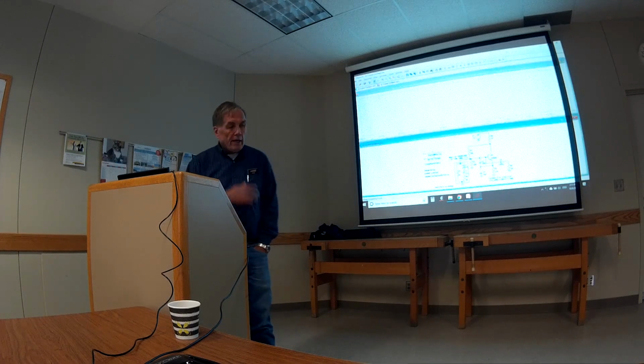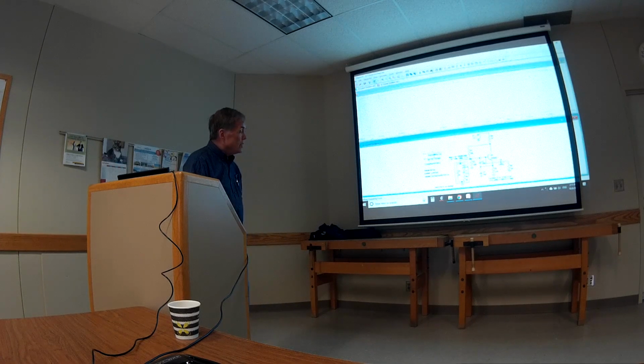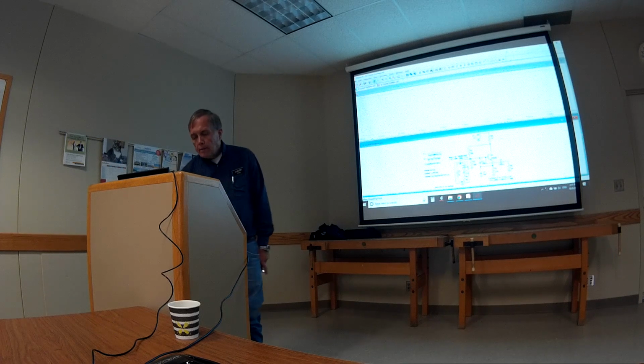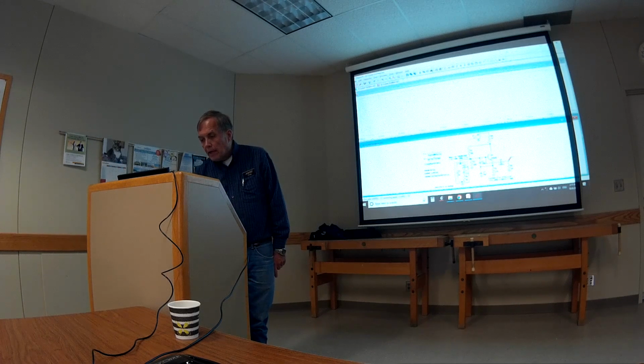Oh, by the way, I connected one other thing to it. You can see, I connected this feed-through capacitor and a 10 ohm resistor. I put a load on there so we can look at this spot here. Okay, just to terminate it a little bit differently.